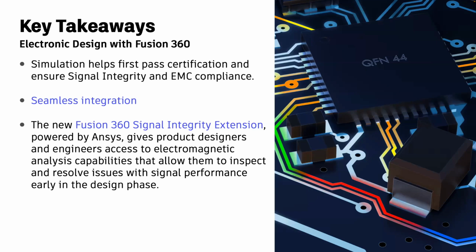Number two is it's fully integrated. This is not a post process. This is fully integrated into Fusion 360. So as you're routing your lines, you're able to find out exactly what your time delay is, what the impedance, capacitance, inductance, and resistance on the line are as well. And these are results that could be downloaded, right? Jorge, you want to tell us a little bit about what you could do if you download all these results on your trace?